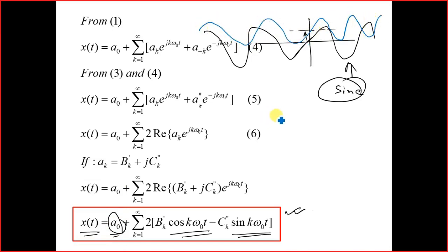Right? Now, under this condition, you can represent the above signal using either the cos or sine component, definitely yes. However, how will you take into account this shift in the baseline? From 0 it has now come to say a 1 volt component, right? Now how do you govern this? This is governed by this A0 component. Am I clear?